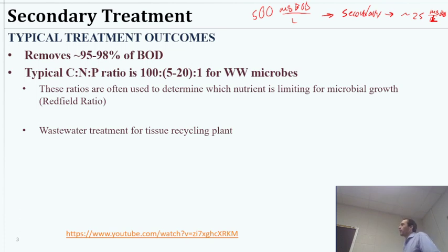So that puts us down to a pretty good spot. Of course, if you think about the oxygen saturation that is possible in water, which is in the 8 to 10 milligrams per liter range, that could still deprive that water of oxygen pretty quick once microbes are allowed to consume it. So in that case, starting with a high strength and with a 95%, that may not be enough. However, if you have a large body of water that's receiving this wastewater, perhaps it is sufficient.